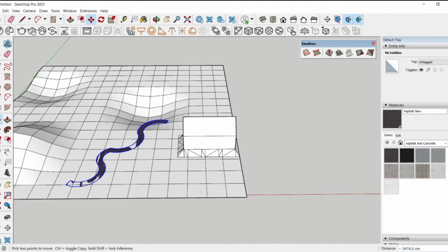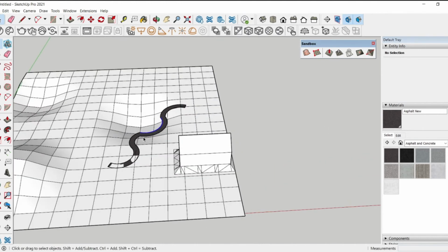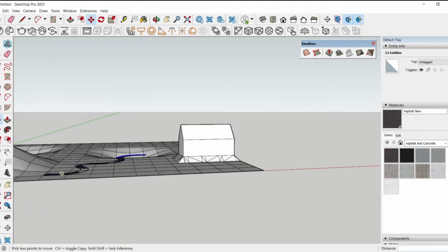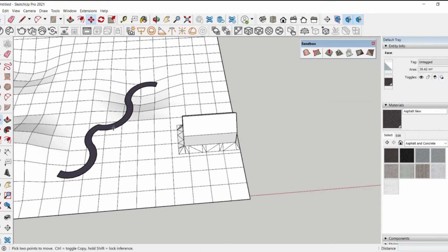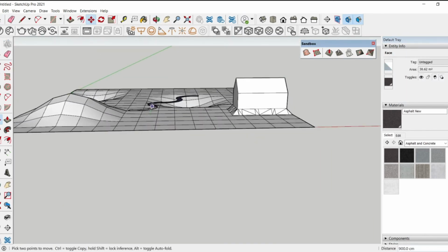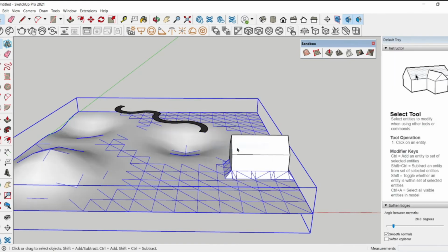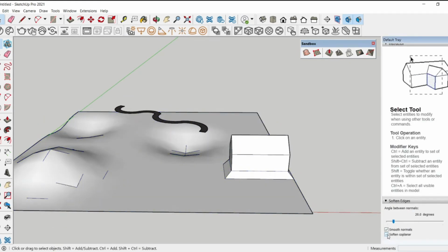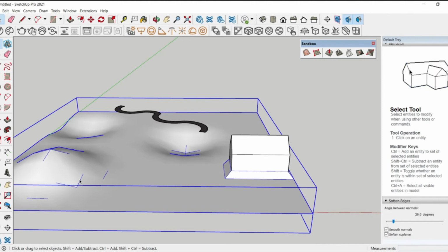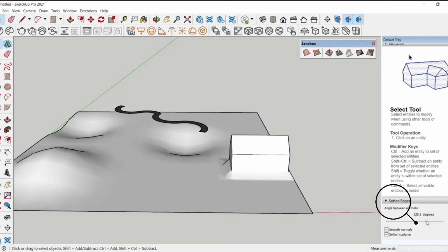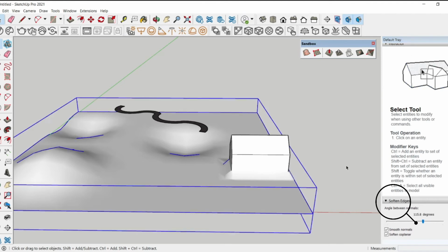However, to see the outlines of the road, I need to clear my terrain of all lines, points and segments. Right-click on it, and under Soften/Smooth Edges, the two checkboxes on the right need to be turned on. Also, you can adjust the scale degrees on the right.